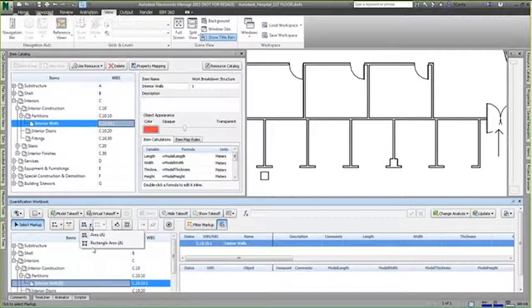So you can do an area and a rectangular area, so polygonal and rectangular. And then you have a series of fills. If you want to do a quick surrounding element, you can do a bucket fill. A quick box, which is difficult to describe, so I'll show it to you. You'll see that some of these icons will light up once I've selected them. And last but not least, you'll have a count takeoff that you can add for elements that you want to get a count of.